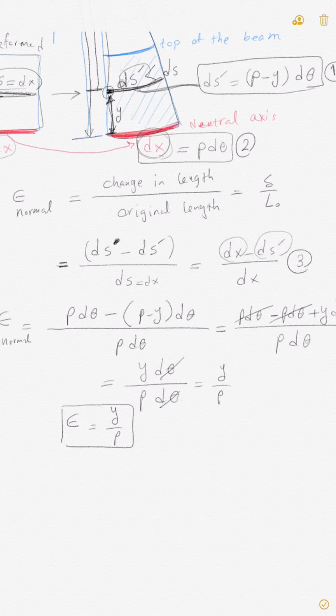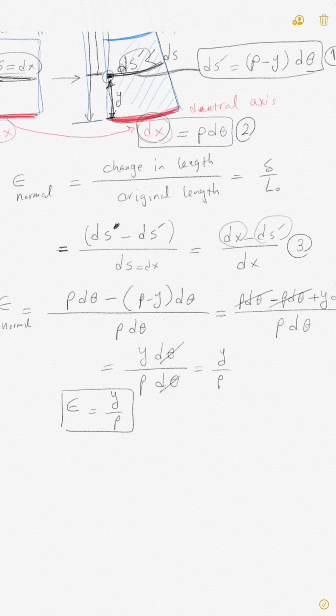That's one equation. But what was epsilon? Go back to Hooke's law. Sigma is equal to E epsilon. This was valid in the normal direction. Look, this is normal strain, and this is normal stress, E the Young's modulus of elasticity, this is not the shear modulus, right? It's the Young's modulus of elasticity, almost twice the shear modulus of elasticity, times epsilon.